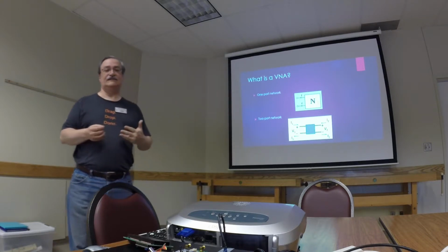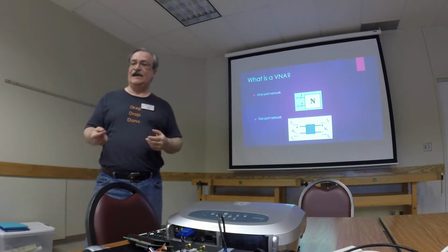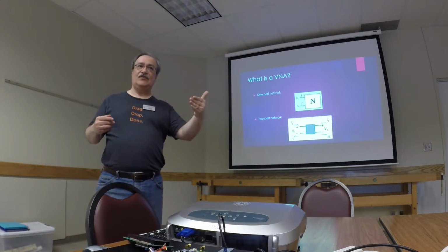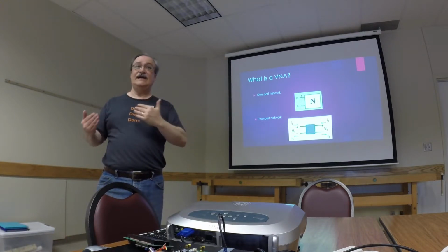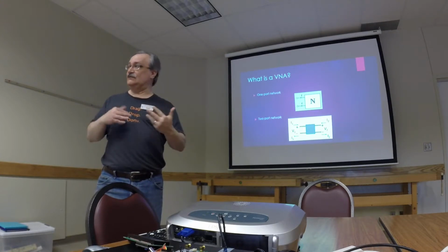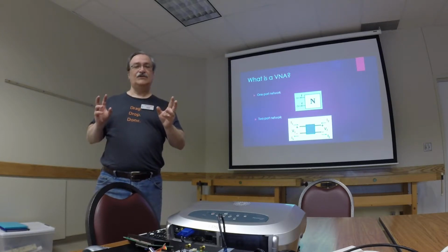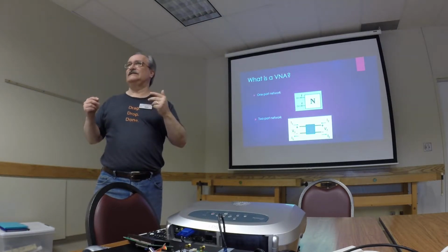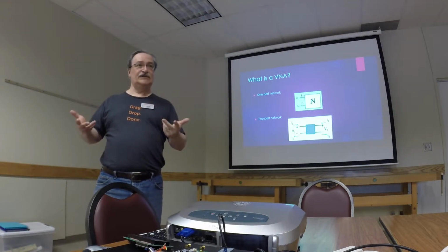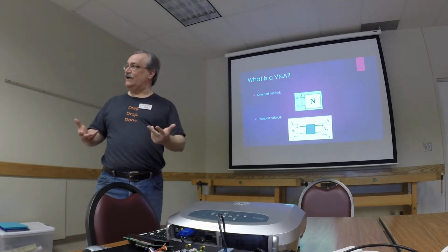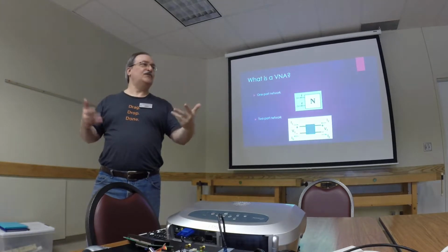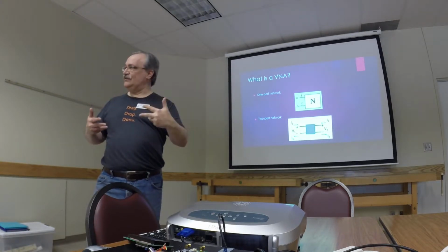Two-port network analysis, which is really where vector network analyzers excel, really looks at both the input and the output. And when you get to S parameters and other parameters, which we'll talk about soon, then what you really have to do is say, if I'm trying to match, let's say, a mixer circuit or an IF amplifier, then I know I've got an input and an output. How do I characterize the input impedance and the output impedance?